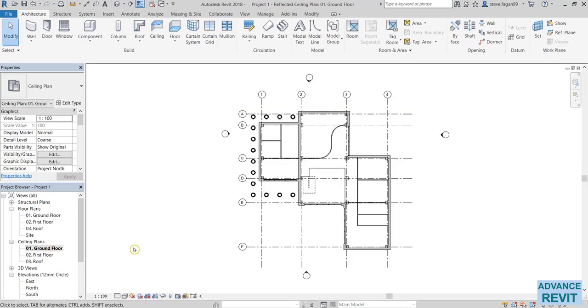If we double click to open up our ground floor plan, the ceilings ground floor plan is simply the actual ground floor plus 2,600 by default above. So when we draw our actual ceilings on the plan, they'll automatically be placed at 2,600 above the ground floor level. We can obviously adjust this after we've placed it. So to place the ceiling, we'll go to our ceiling tool.